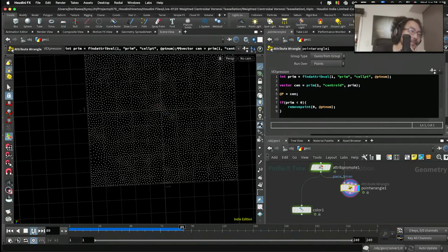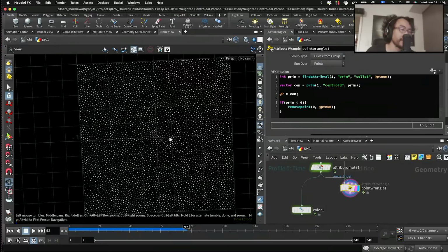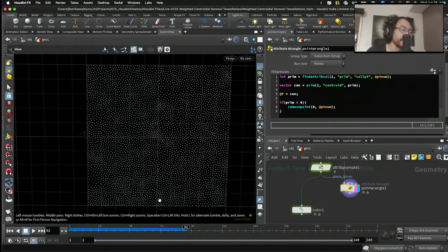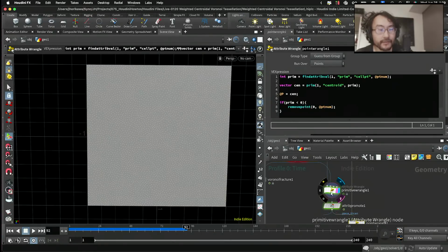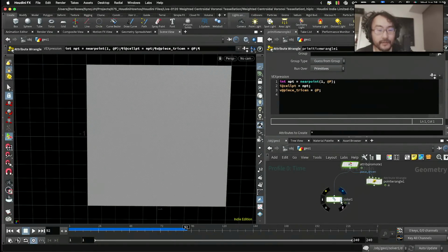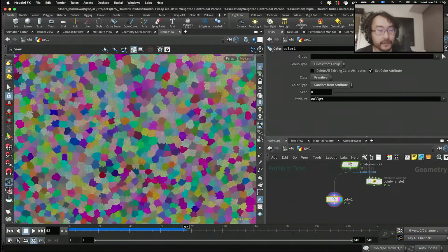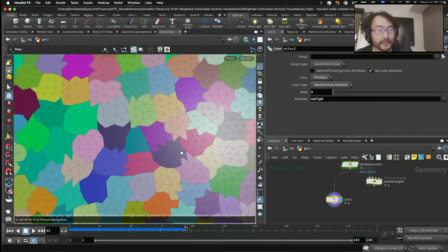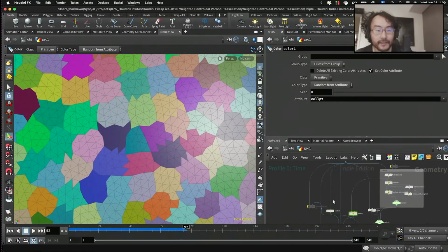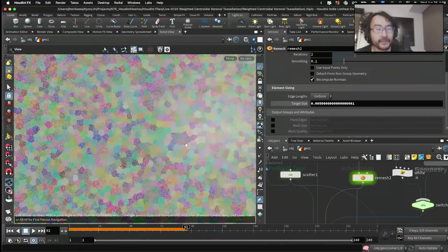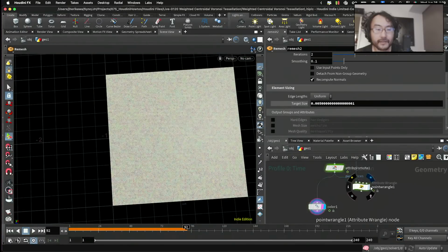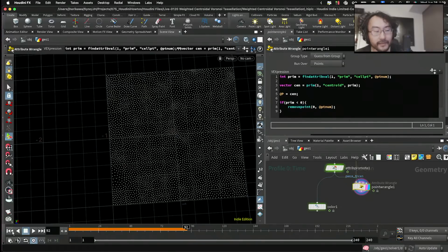It's not really doing what I want. And as you can see, the precision is not really good. Probably due to the resolution of the Voronoi cell itself. Maybe I should make the original remesh geometry a bit higher res to have more crisp edges to get a better result. But if you do that, you get a slower result.